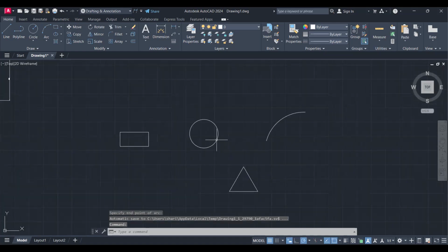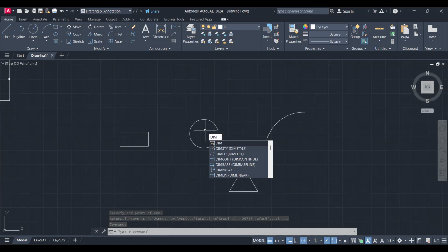Okay. I want to calculate this dimension by the shortcut key, which is DIM. Okay, and this is the same as this option. Why does this happen? Because when we click on this line, this will appear. No need to select the points. It directly shows your dimension value.